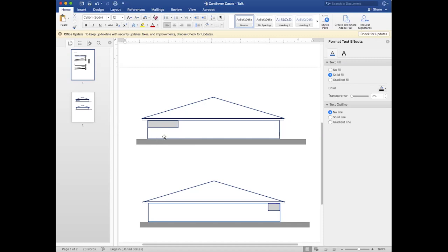So what to use? We didn't want to use a flitch beam. That's old construction, using sawn lumber with steel plates sandwiched between it, because it requires a lot of times a different trade, a trade that can bore through steel plates and carriage bolt it all together to sandwich that header beam that needs to go up above the window.